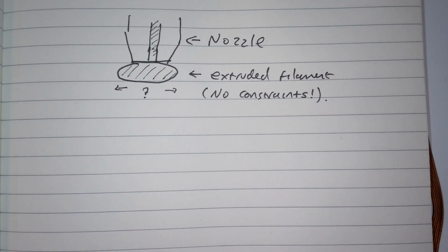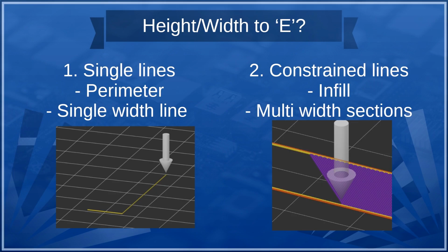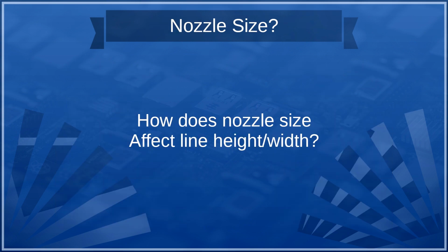When you're extruding with lines either side, though, you can see that the width parameter is easier to enforce. In fact, it's always enforced, as each consecutive line can be spaced by the movement of the nozzle, or, to put it another way, it's going to fit in there because it's the only squishy thing, so it doesn't get much choice. The second question, if you can still remember what that was, is easier to answer than the first.